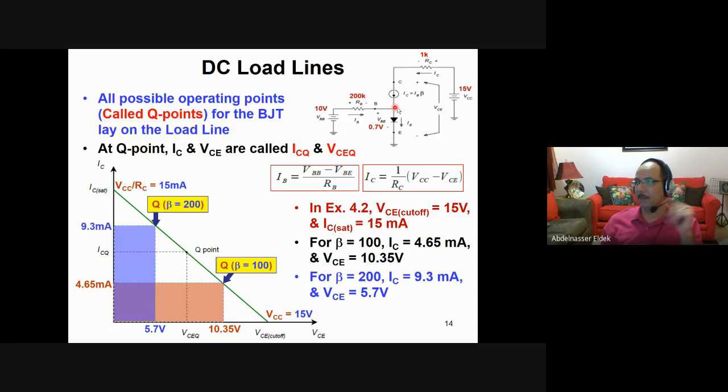When you have a ground, and you have what we call base bias, when we have a voltage here and a voltage here, and we have a ground here, this is a problem, that it is unstable. Why? Because beta is subject to change. Beta is a function of the temperature. And as I said, when you have a current, the current will heat the transistor, and when it heats the transistor, beta is increasing.